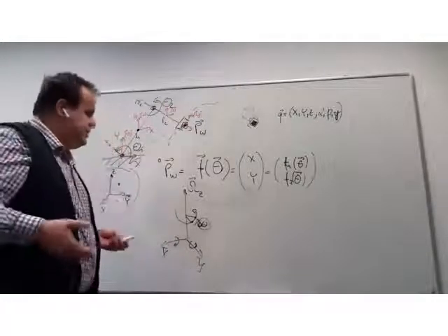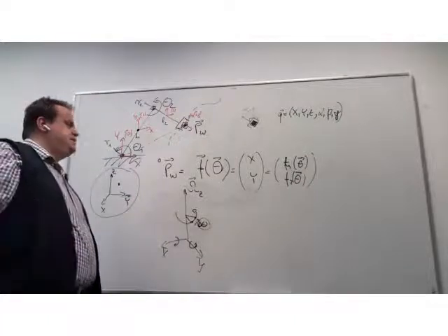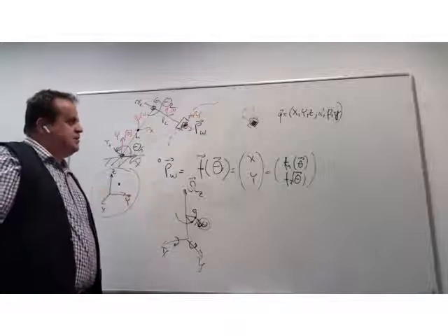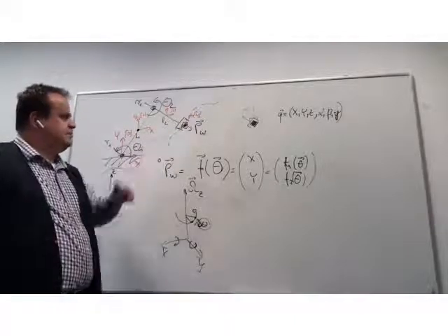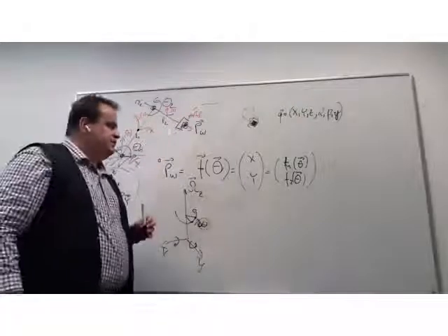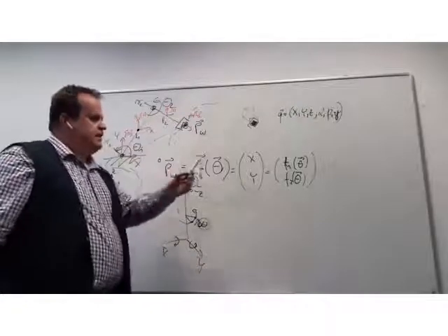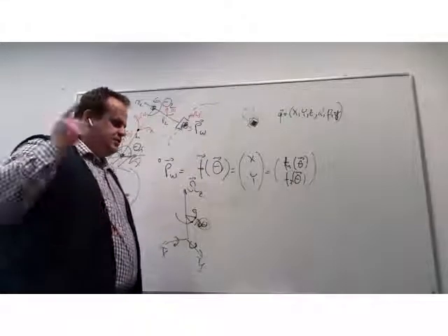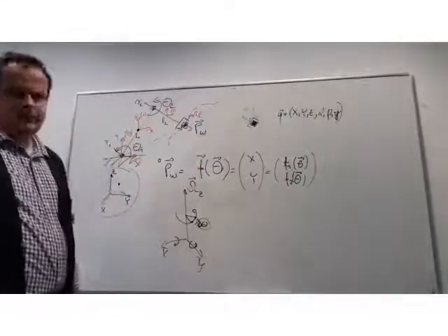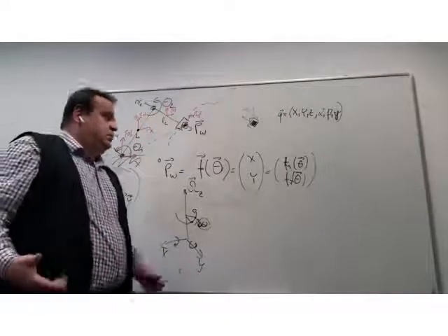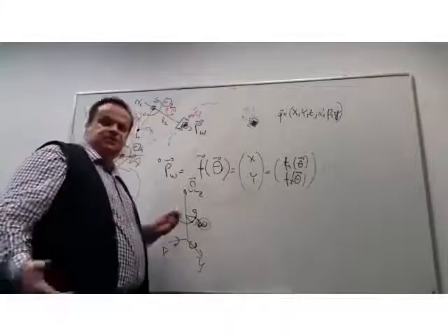So what we will require, the pose being position and orientation of the end effector, is defined, in the general case, by 6 parameters, 3 of them describing the translation in the right-handed coordinate frame, and 3 of them describing the rotation as 3 angles, which need to be specified.